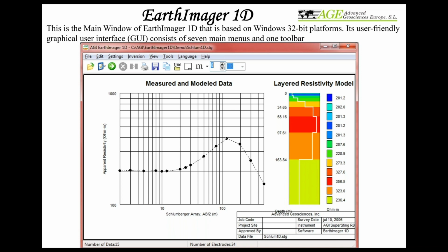Now I continue our measurement, and then this curve turns down again. That means we're getting into the third layer, the third zone. So that's how you continue. Any change you see on your curve, but these are smooth changes, not sharp changes. Sharp changes generally mean noise or something else during the field measurement. So sharp changes cannot generally be considered another layer. But smooth changes, yes, you always consider as another layer.